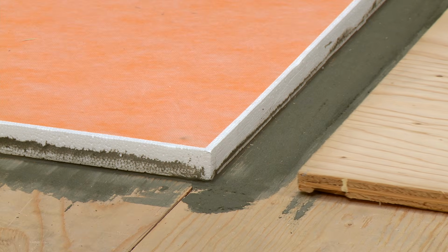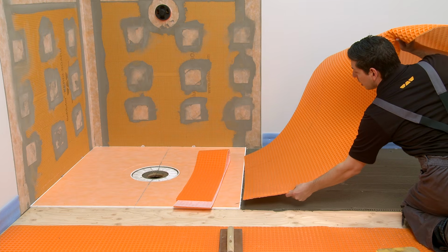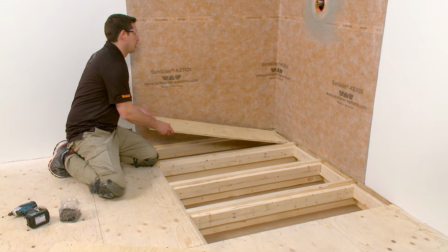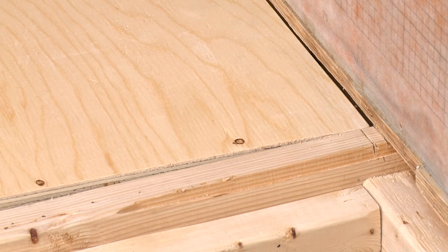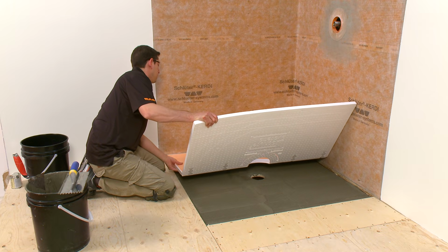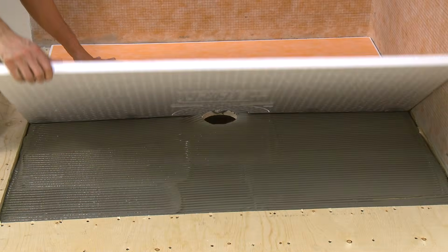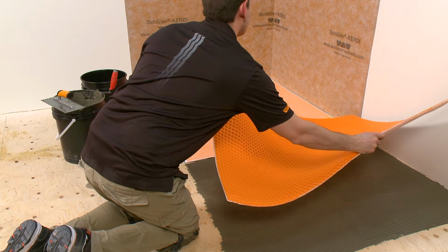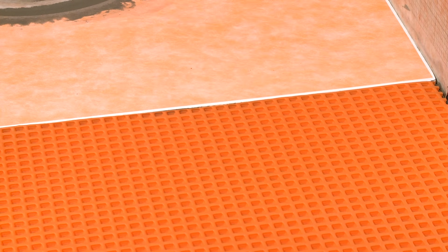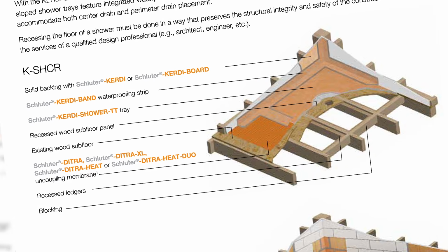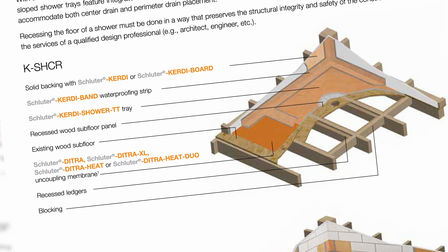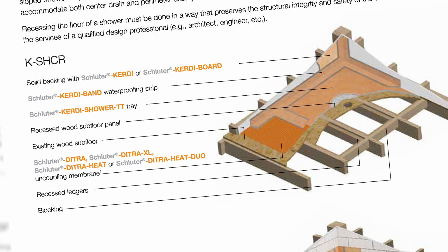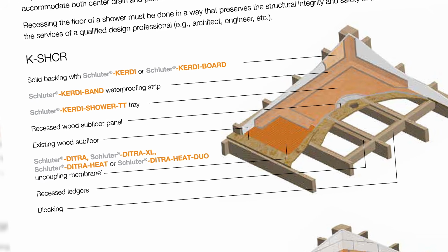Before you begin, you'll need to decide if you're going to build up the bathroom floor outside the shower area or recess the floor within the shower area. A recessed shower floor allows for the installation of a sloped mortar bed or a prefabricated shower tray that is flush with the surrounding bathroom floor. Let's take a look at one way to recess a wood subfloor. Please refer to detail K-SHCR for all requirements.